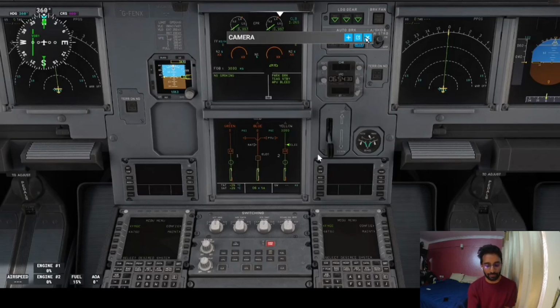Okay, the PTU knows it is the ground staff operating the cargo door. So the electric pump will run, which is that sound you might hear after parking if you are traveling as a passenger. Once the aircraft is stopped, you will hear a beep sound, right? That is the electric pump running. It is pressurizing the yellow system. Clear? Makes sense? So the yellow pump automatically stops when the cargo door is fully open and the yellow depressurizes. Because if there is no pump, there is nothing else to pressurize the system, right?